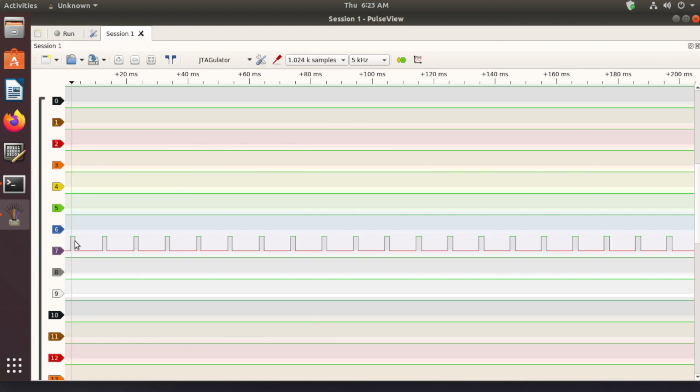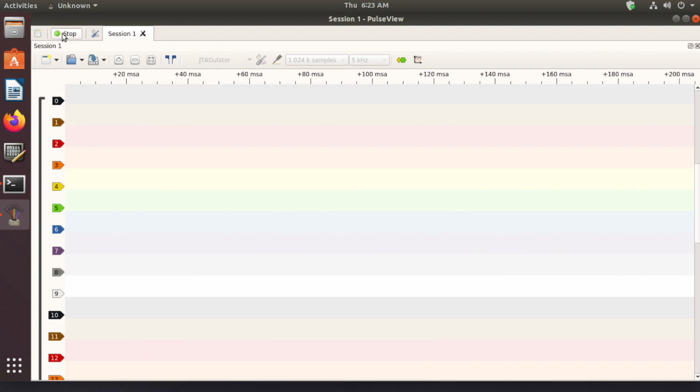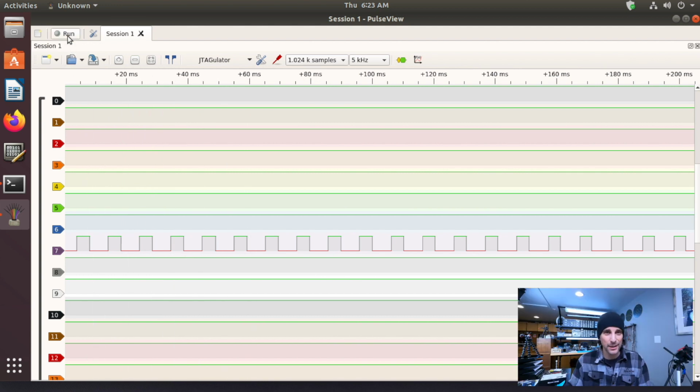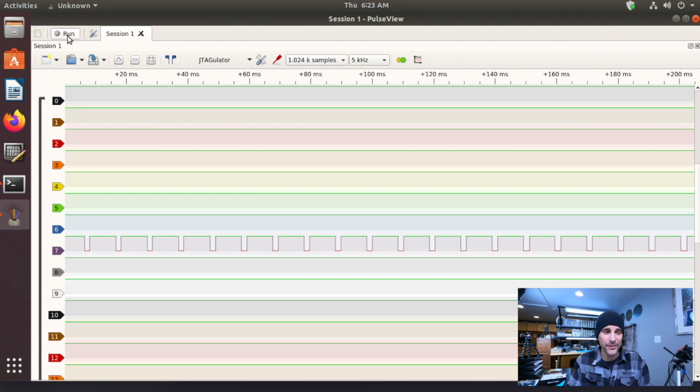And we see on channel 7, here's the little pulse stream. Hit it again, same channel, but the pulse is a little bit wider because that PWM code we're running is varying that duty cycle. So we definitely see activity on that line. What I would probably do at this stage if I was really looking at a system is say, okay, I see activity there, so I would then go and turn on my scope and see what's actually there.